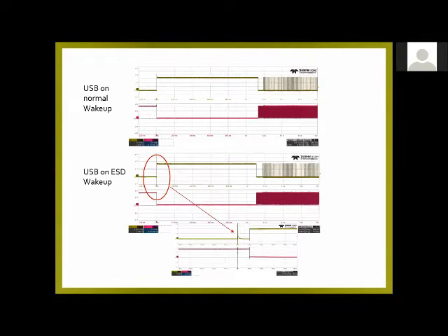Okay. And the keyboard, we did a lot of study on this, trying to figure out what it was. Is it the mouse? Is it the monitor or whatever? And we found it, that narrowed it down to the keyboard, because you start unplugging things and soon you find out, yes, it's the keyboard that's the cause. So we kept zapping near things until we found what was the most susceptible. And the keyboard was a USB keyboard.